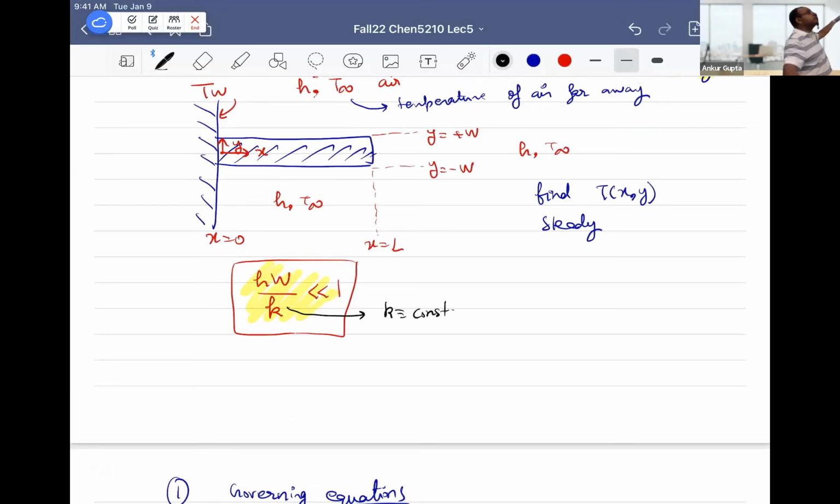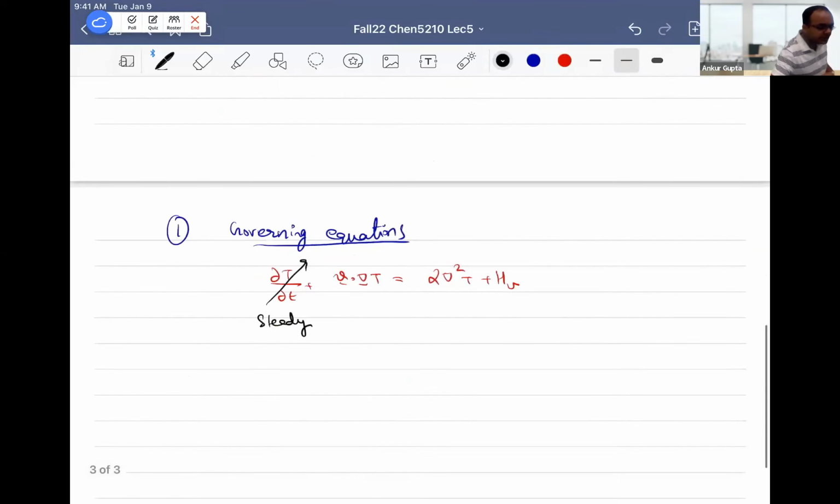In a fluid phase, it's a little different. A solid block doesn't have any velocity, it's just static. When we say convection, remember that a solid system has a different meaning. It's a rigid body, whereas a fluid may have a local velocity. This is zero because the solid is stationary. What about HV? Do we have any volumetric generation?